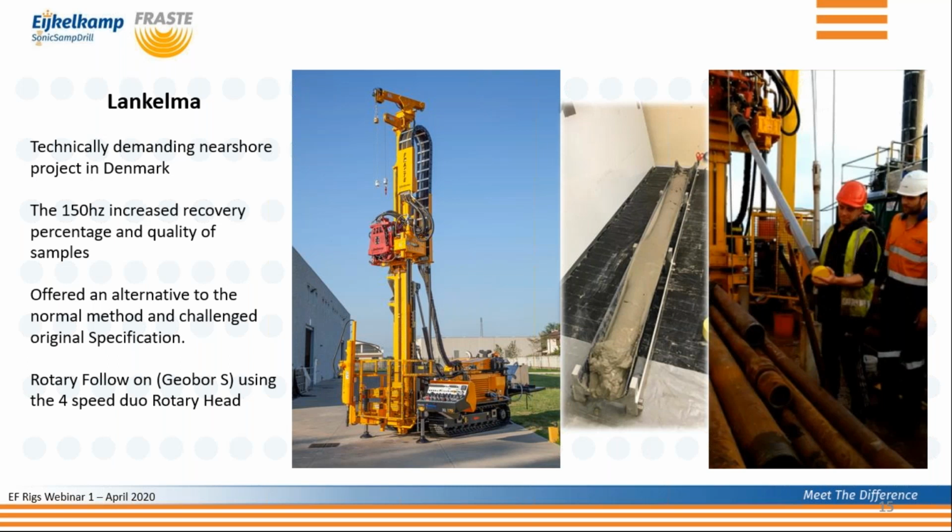Once the struggle within the superficial layers was successfully conquered, the coreable material was later encountered, and it was drilled with ease using the rotary Geobore S methods. The drilling crew were able to drill a 1.5 meter core run every 6 to 10 minutes, with the system being quickly deployed using our dual Sonic rotary drilling rig.